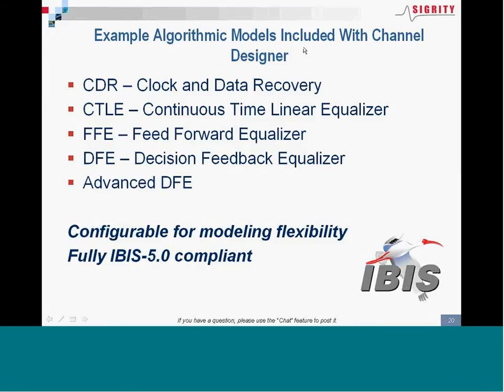These are some of the example algorithmic models that are included with Channel Designer. There's a CDR, clock and data recovery model, continuous time linear equalizer, feed-forward equalizer, decision feedback equalizer. These two you saw in the demo, and an advanced DFE model also. The ones that are included with the tool are very programmable.